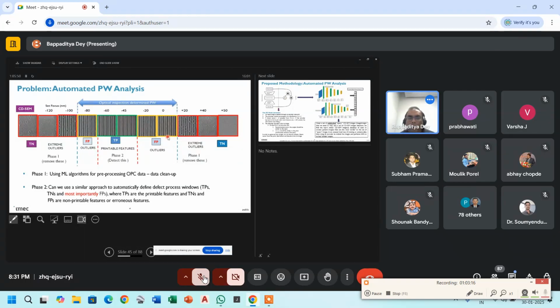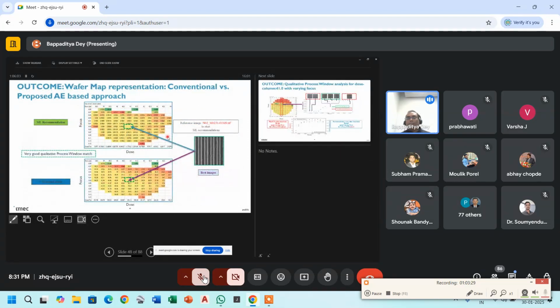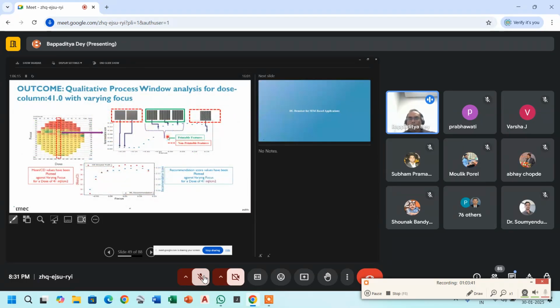So you can also make a mistake, right? Even though you know all these process parameters, dose, focus, and everything is known to you. So what we try to do is formulate an unsupervised machine learning model that doesn't know all these different parameters. I'll just throw the image, and the model can do this dissection or difference by itself without knowing any of the BKM or the parameters, what is dose and focus.